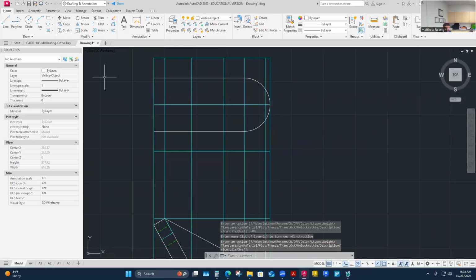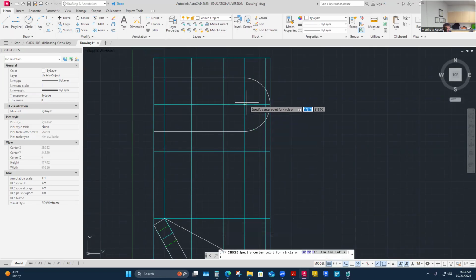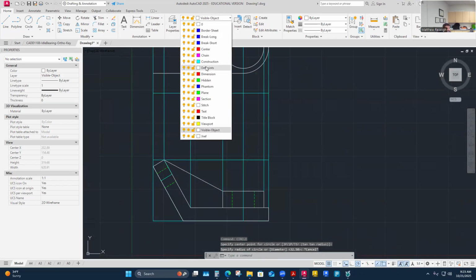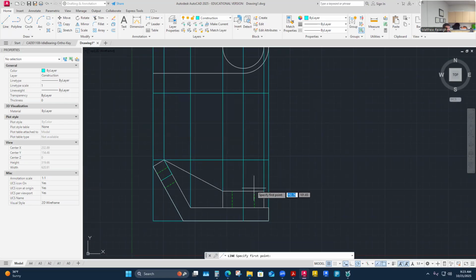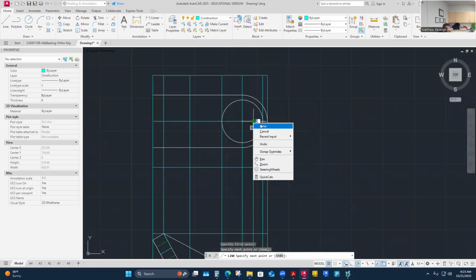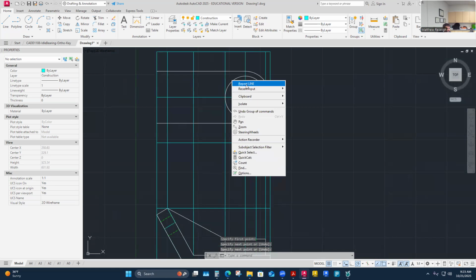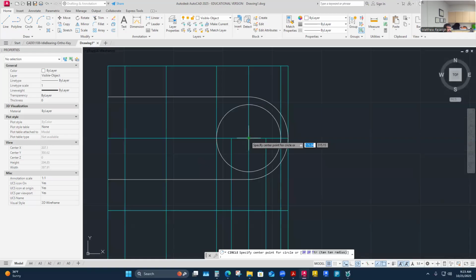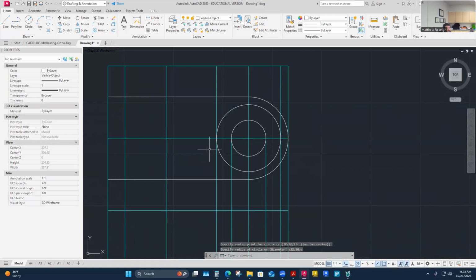And it's got my other diameter holes, which I've already pulled. So I can just go ahead and pull those two holes here. This diameter is the outer 65, 32 and a half. That looks correct. And then this other one, I haven't projected up, but I can. It's not totally necessary to do this. You could have just drawn it in and put in the number, but this hole would be like this.